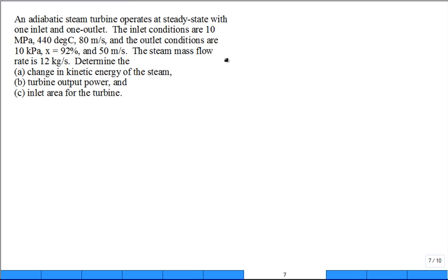This is just a steam turbine. Often we just draw it like this. Here's our steam turbine. Why do we draw it like that? Because it goes through a sequence of expanding, rotating rotors, stators, pushing blades, and then a rotating shaft. And out here comes a rotating shaft, some shaft that cuts across the boundary of a control volume that surrounds that steam turbine, and steam comes out down here after it's expanded. You can look at pictures on the internet or even in our textbook on steam turbines.